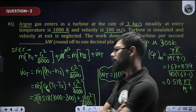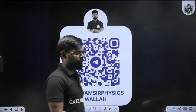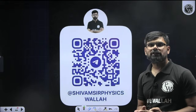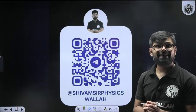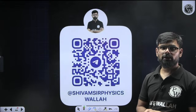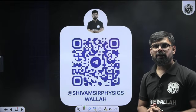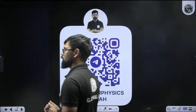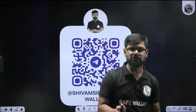Okay. Next. Okay. So this is all about today's lecture. Today we learned about open system, steady flow open system. The things that you have to remember from today's lecture: to analyze open system steady flow, mass balance is required, means m1 dot is equal to m2 dot, that can be written as rho 1 a1 c1 is equal to rho 2 a2 c2. And another one that you need is the energy flow, the steady flow energy equation.